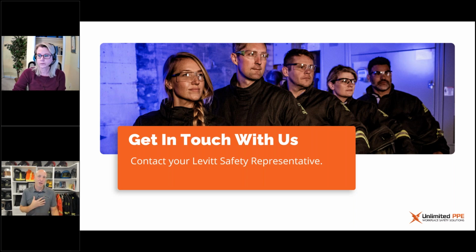earmuffs, I often believe earmuffs are required as dual hearing protection, just simply based on the exposure level. But please don't shoot the messenger. I don't think it's being used properly in terms of selecting your hearing protection and what would be adequate for its attenuation level. I know the testing that's been done or performed in the industry. I've seen tests where we've actually taken earplugs and tied them on a string and exposed it to an arc flash, and all the earplugs light up.